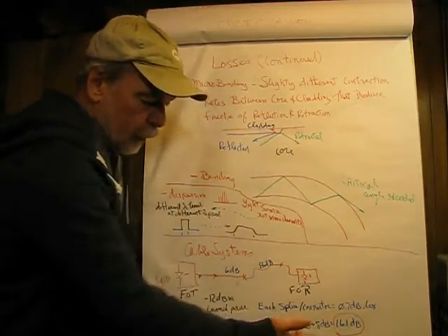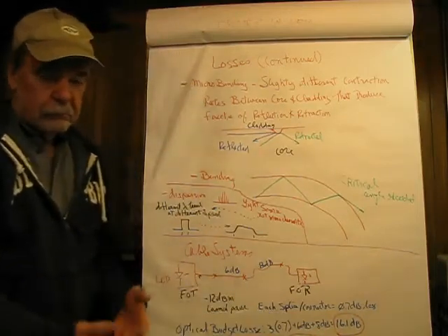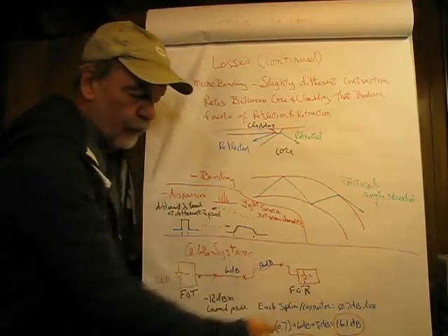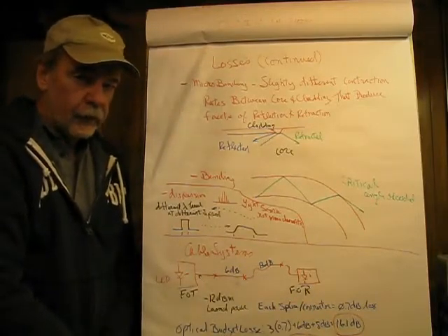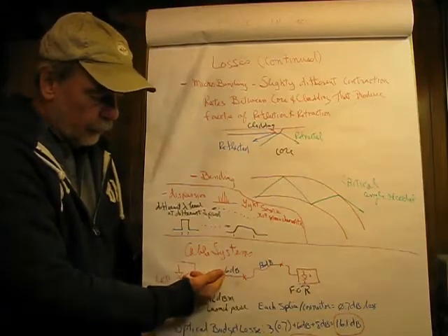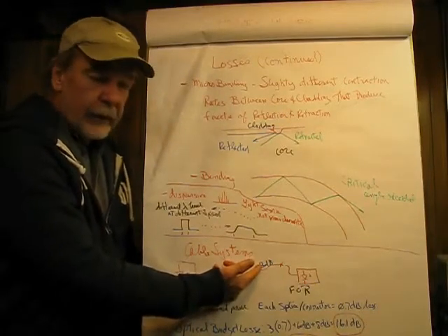Is it too high or too low? Don't know. How do we find out? We read the book. This is going into a fiber optic receiver. If it's too low, we've got a bad system design, or maybe one of these cables should be, say, 3 dB, but it's 8.